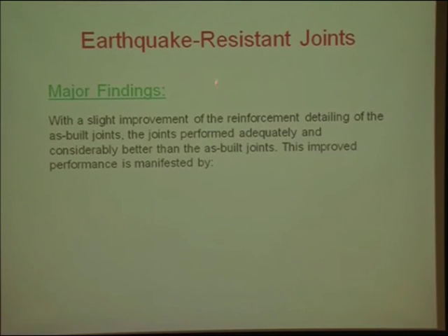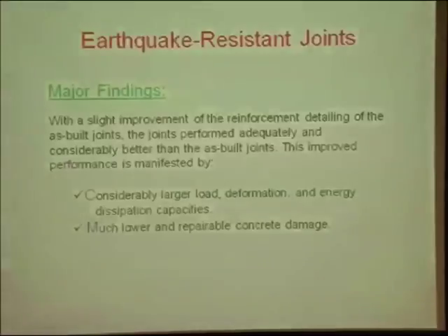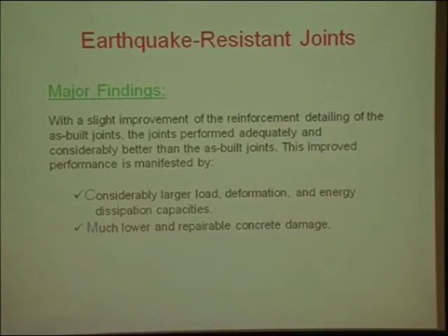The earthquake-resistant joints, with a slight improvement of the reinforcement detailing of the as-built joints, performed adequately and considerably better than the as-built joints. This improved performance is manifested by considerably larger load-deformation and energy dissipation capacities and much lower and repairable concrete damage. We even repaired these after they were damaged. We repaired them and we tested them again, and they performed beautifully.